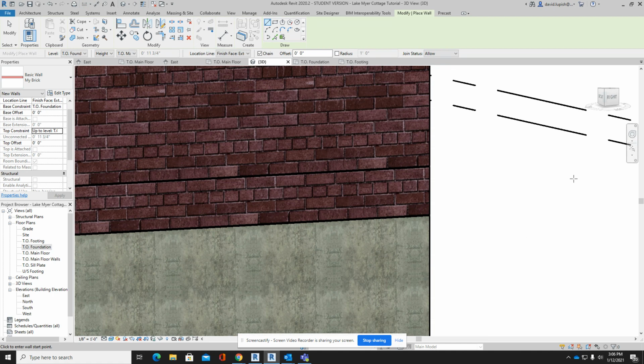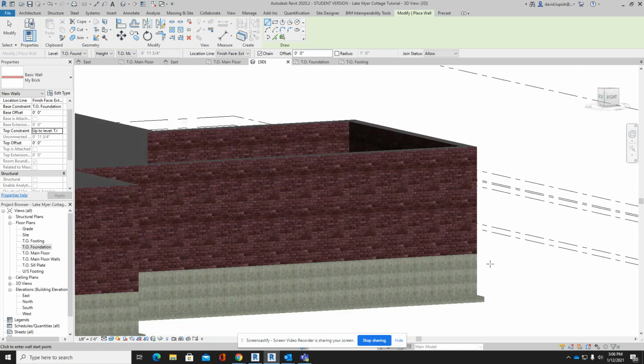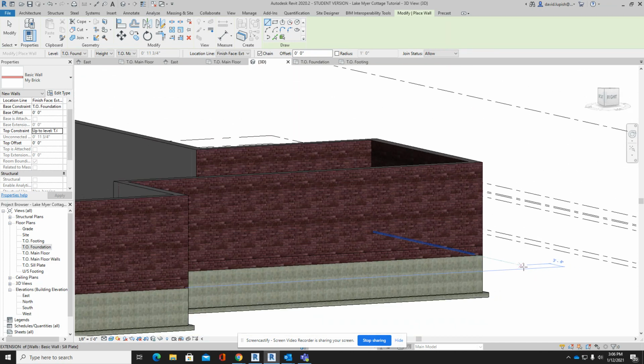So again, quick and easy to do, guys, between setting up the custom wall type for my exterior finish and actually going through and completing the process. It's a couple minutes' worth of work. And when I look at my three-dimensional view of my project, that is how it should look when it's rendered, right? We shouldn't see the edge of the floor.